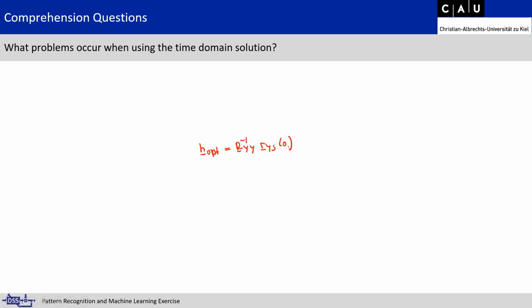You see here that we require two different quantities. The autocorrelation matrix Ryy can be computed easily. The inconvenience here is everything that comes along with the required matrix inversion, but that's not the problem I want to talk about here. The cross-correlation vector, however, is an actual problem, since for straightforward computation, access to the clean desired signal is necessary. We need the cross-correlation between the observed signal and the desired signal. But if we had access to the desired signal, there would no longer be a point in applying a Wiener filter. So the time domain solution doesn't actually help us with the problem that we set.